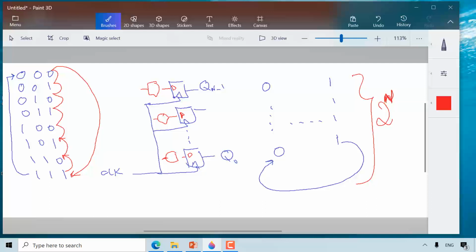These are just academic flip-flops that are meant to be part of the basic information that you take in digital class. In practice, they have very limited use. Everybody uses the D flip-flop, which is easier to design and easier to code. These are the kind of flip-flops that we have in practice.